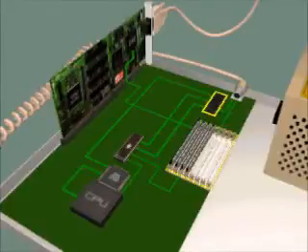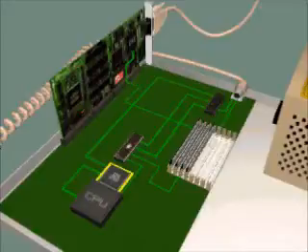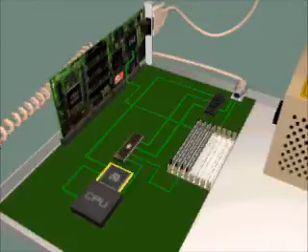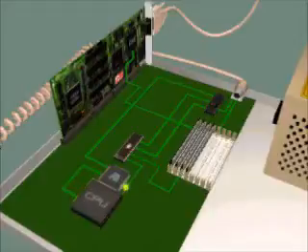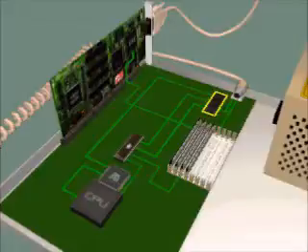RAM holds your letter until the PC is ready to use it. At the same time, the keyboard's microprocessor sends a signal to another device, the interrupt controller. It tells your PC to stop what it's doing and pay attention to the waiting keystroke. Next, the interrupt controller sends a signal to the CPU, which passes the task off to the ROM BIOS chip, which yells up to the keyboard controller, "Hey, where's that scan code anyway?" Based on what key has been pressed, the software performs some action, usually displaying a character on the screen.